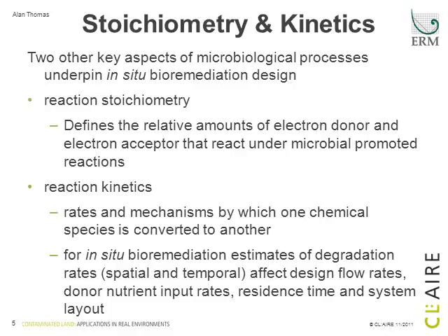Two key aspects underpin microbial process design. It's not a black box as many people think, but it really is an engineered process. Two essentials to that are the reaction stoichiometry, and that's basically, in simple terms, the amount of reactants you need to effect a microbial process. So it's really the balance, if you like, between adding oxygen compared to the mass of hydrocarbons that you have present. And the second thing is the reaction kinetics. How quick is the reaction occurring? And I think you need to balance those two elements to underpin really any in situ bioremediation design.